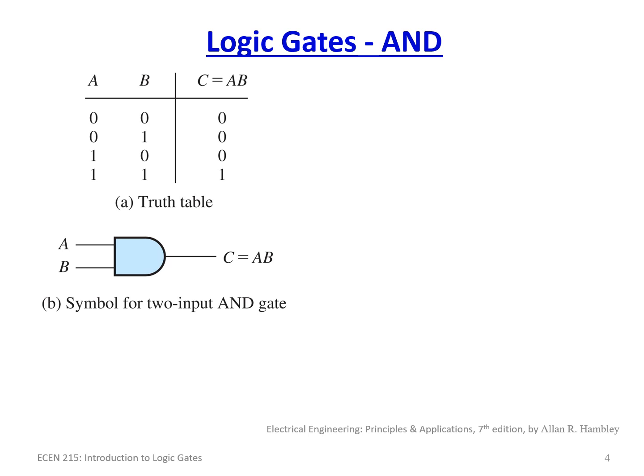Now let's just look at logic gates. So we have all of this Boolean algebra that we've looked at. And say we have a function here, C is equal to AB. That's our function. So we can represent that with a logic gate. You can buy an integrated circuit that implements this particular function. It has 2 inputs and 1 output.